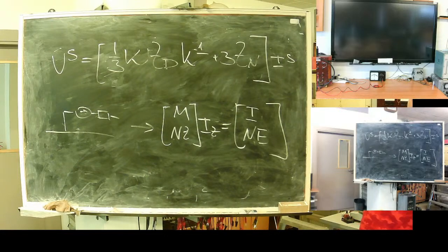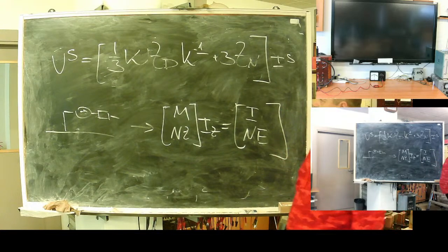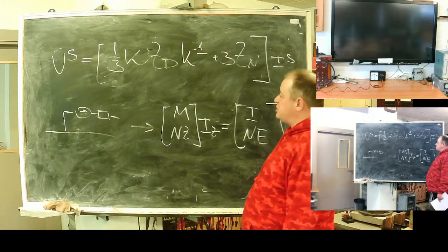Sequence networks also. Any sequence network, direct, negative, zero sequence, can be represented as an equation system connecting current sources and EMFs with currents and voltages, if we speak of a nodal voltage system.